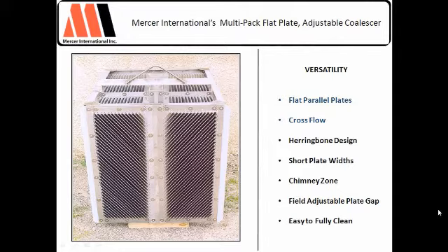Once solids lodge in a plate, they grow off of each other and the fouling goes much more quickly. A cross-flow design. In today's marketplace, all the real designers go with a cross-flow design. Phil mentioned the upflows and the downflows. They're both countercurrent, meaning one of the components, like solids, has to fight against the flow of water. When it does that, it tends to ramp up and plug.